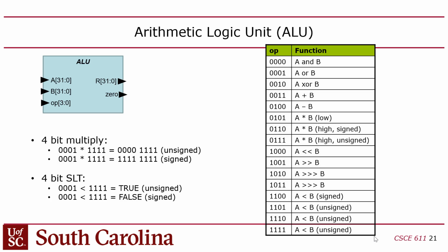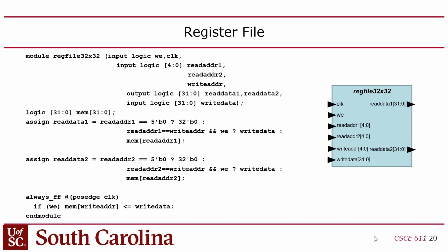I'll talk about that because we have an I/O instruction. So you need a mux for the write data because we need a way to get the switch values on the FPGA board into the register file. So we need a data path for that. I'll talk about that in a minute. But yeah, you got it. Pretty much you've summarized what this lab is all about. We're going to give you the ALU, you just have to connect these things together. And you're right, read data 1 and read data 2 are connected to A and B. So your goal is to figure out those connections.